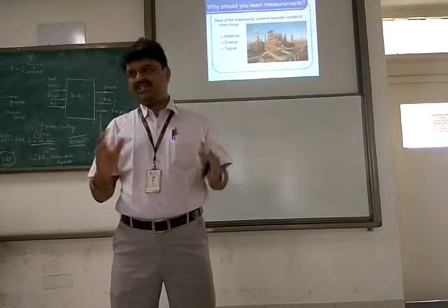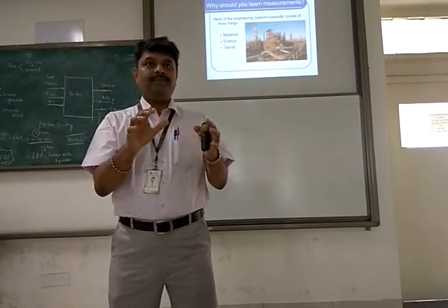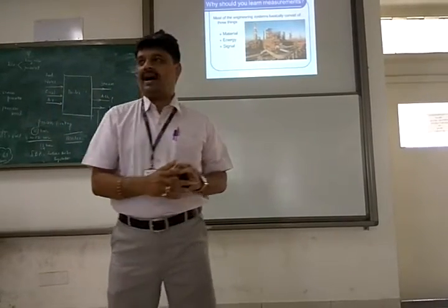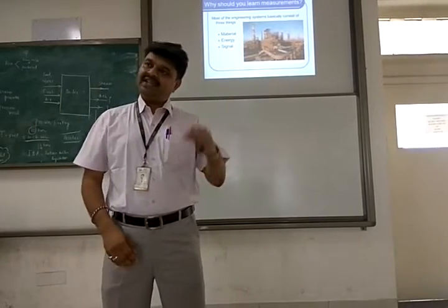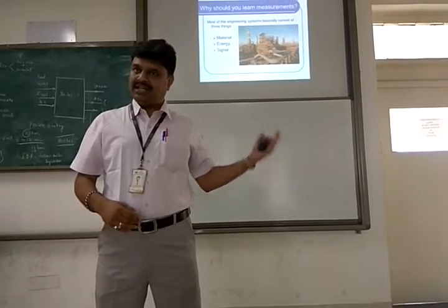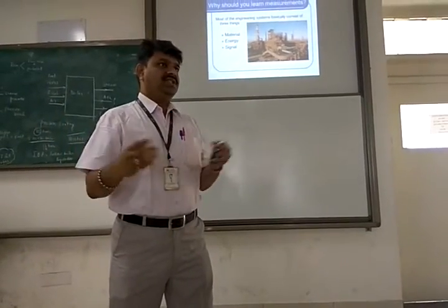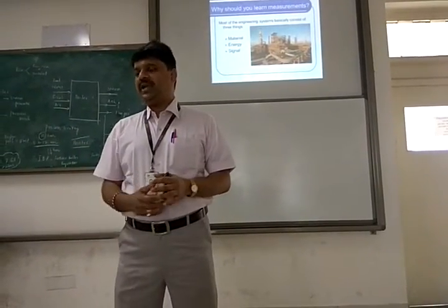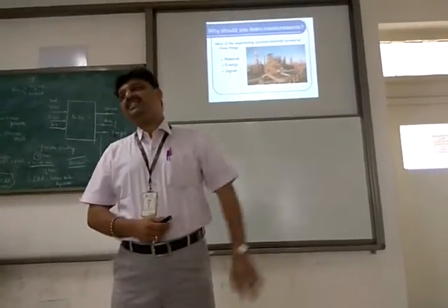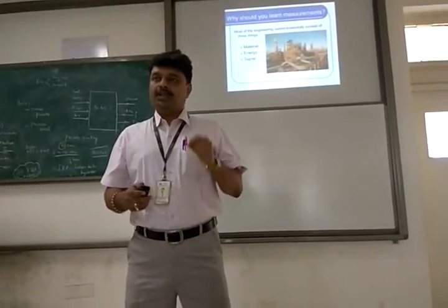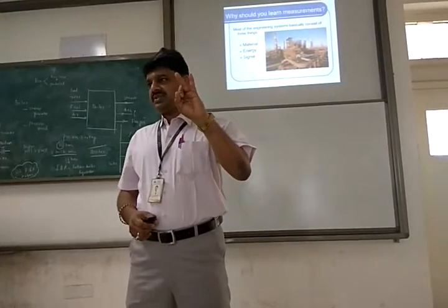Heat energy is the energy, not just temperature. Let's say if you maintain 340 degrees Celsius, the injection molding machine will work, for example. If it goes to 350, a lot of material will be wasted. If it is maintained at a lower temperature, say 320, you will not get plastic parts completely filled. You will get pieces with defects, so your material will be wasted. Whatever energy you used for heating the material, you will pay the current bill unnecessarily. Once the signal is lost, your material is lost, and your energy is lost.